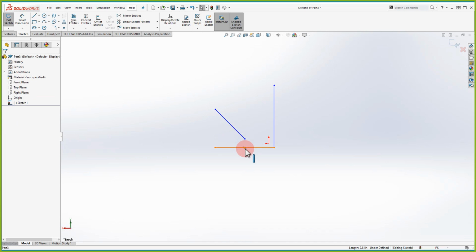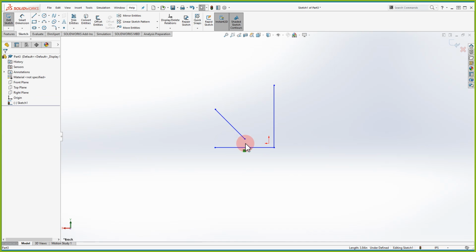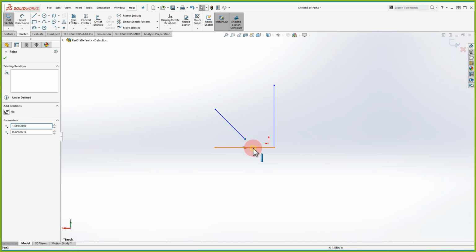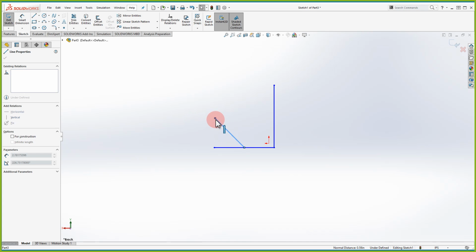And if I wanted to make the midpoint of this line, I click the point, the object, or the line in this case, from here to here, holding control. I always hold control when you're choosing the two lines, and I could do midpoint of that object. So now when I move it, bigger or smaller, it's always going to stay in the midpoint of the line.